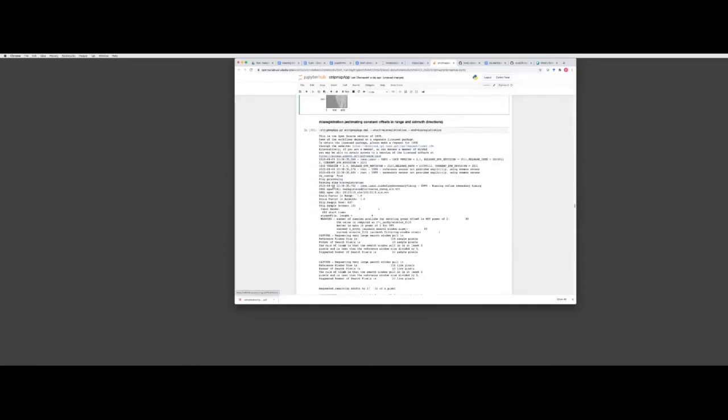And as I said, so far all we have done was just using geometry, using metadata, so there might be errors there for our co-registration. The main source of error is, one, the orbit uncertainty in all cases. But actually these days, we are pretty confident that the main source is delay in troposphere and ionosphere.